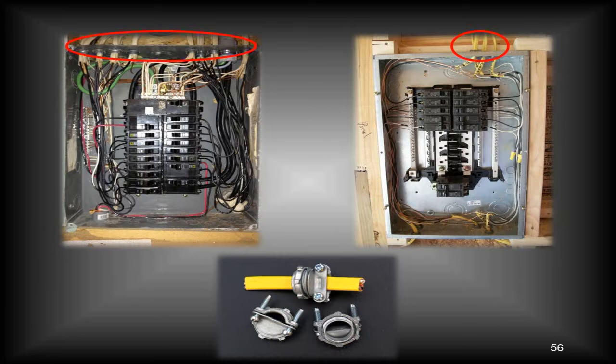And so if a fire were to break out inside of the panel and burn all the sheathing away, and you had two non-metallic wiring methods doubled up in one connector, there would be a huge gap that fire could spread outside of that panel up in through the joists and to the rest of the house. So that is one, and should be adequate enough, reason as to why they don't want you to do that. Sure, it costs more money to put in a new panel and such, but we're talking about structural integrity.